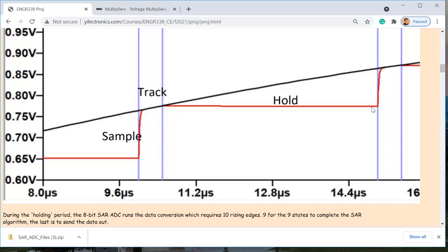Remember I gave you an example: it's a 10 volts VREF, and I have an input at 6.2 volts. They're compared with 5 volts at the very beginning, because the initial state will be 1 followed by 7 zeros, right? And that one is 5 volts. I compare 5 to 6.2 first, and it's apparently smaller than 6.2, so the comparator's output will be 1.